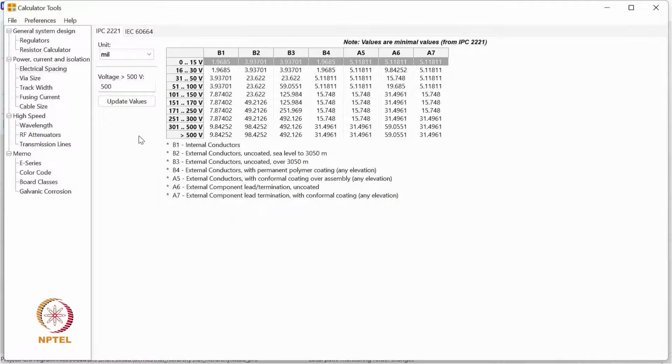So from this electrical isolation, I can find out the spacing which I need to put during PCB design. So while PCB designing, I need to figure out the optimum spacing and draw our traces according to these constraints.